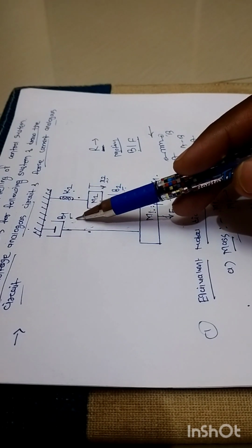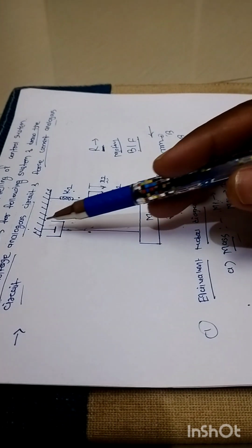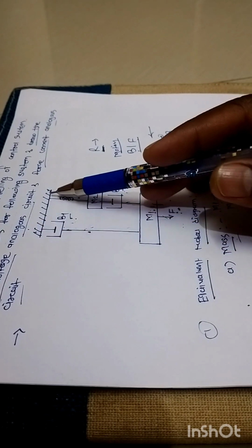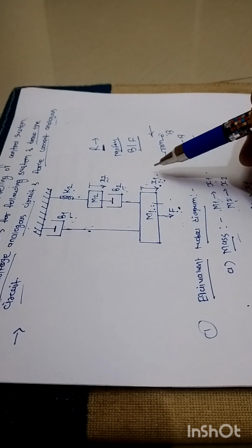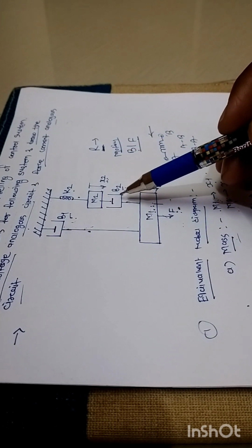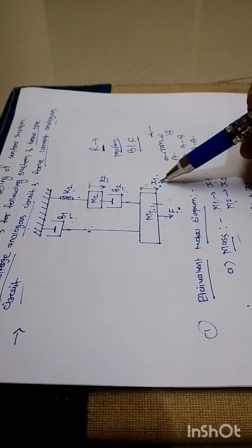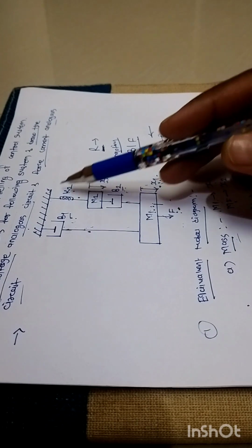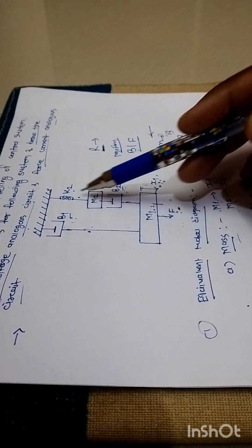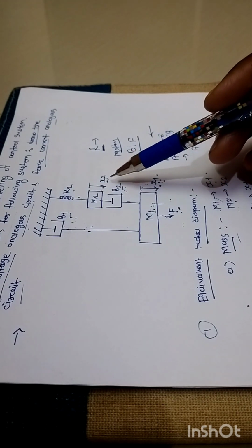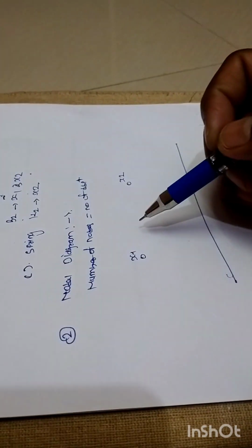How is damper or friction number 1 connected in this mechanical system? The lower end of this damper is connected to the ground axis and the upper end is connected to x1, right? Similarly, how is B2 connected? The lower end of B2 is connected towards x2 and the upper end is terminated towards x1, right? And as far as this spring is concerned, as I told you earlier, the lower end is terminated at the ground surface and the upper end is connected towards displacement number 2, right? Accordingly we need to complete this nodal diagram.